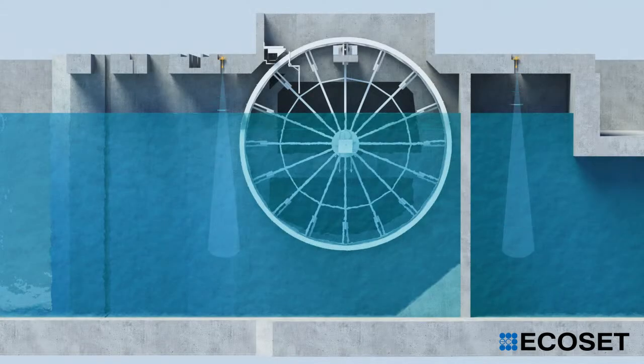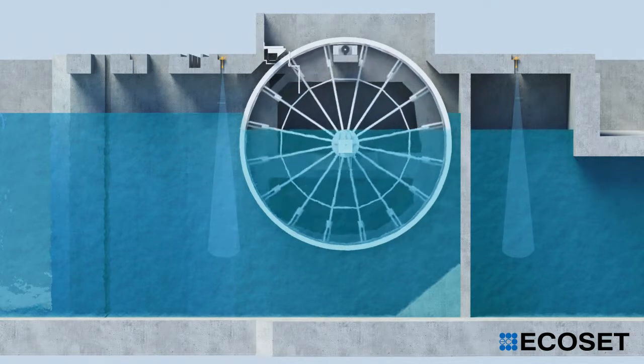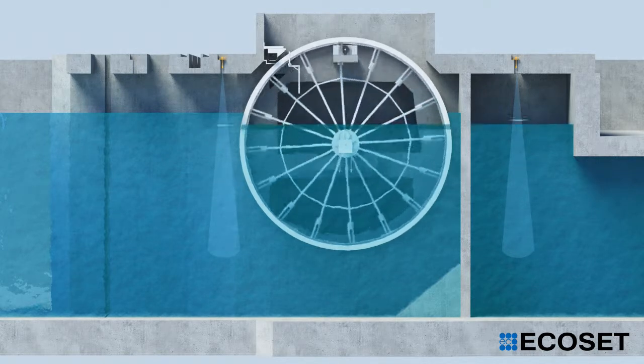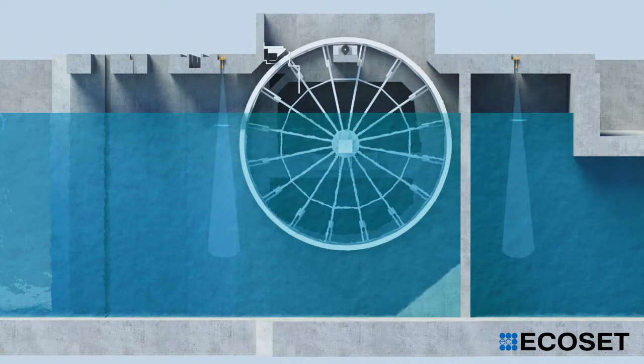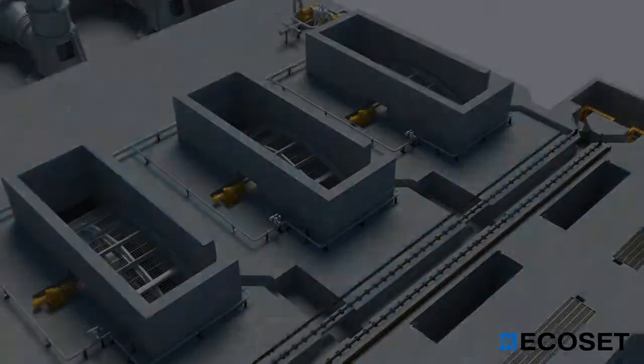Under the operating method of differential level control, drum screen is operated by the value of the water level difference between upstream and downstream of the drum screen. Also, it is operated at low speed or high speed, depending on the water level difference. If the water level difference decreases to low level point, drum screen will be stopped. But before a complete stop, it will be operated for a few minutes to prevent drying and sticking of debris on the wire mesh panel and trough.